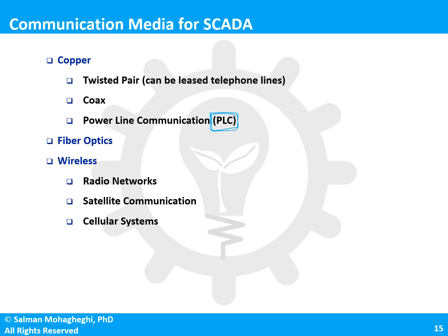Power line communication is a technology in which you superimpose your data on top of your 60 Hertz component. So this is your power line that is, let's say, flowing a particular current signal at 60 Hertz. You add high frequency communication signals on top of this, and then it basically piggybacks on the 60 Hertz component and goes from source to destination.